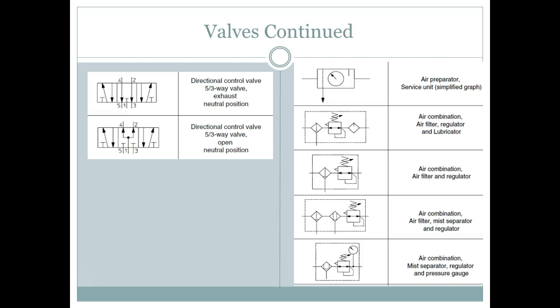We need that because of these cycling compressors, and we talked about that the other day, they cycle. Most standard compressors like you have in the home will compress up to 100 psi, and then drop down to probably 70. But your air tools are designed around 60.